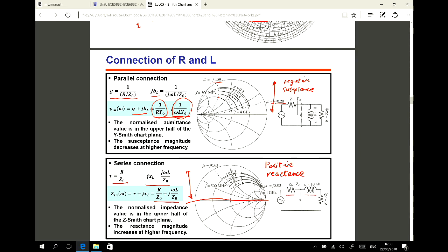And the total Smith chart is 0.5 lambda, right? Lambda by 2. Yes, the whole. Because we had from the previous lecture that if we have a load and a transmission line with lambda by 2, again we have the same load, and it shows the same input impedance as your load.